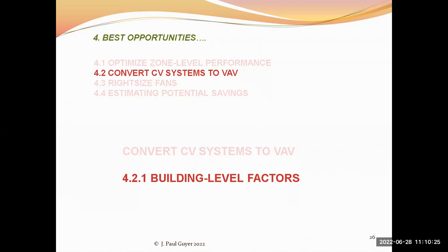In older buildings also, something that you need to be aware of is whether there is an asbestos issue in the building itself. And the rules of the game basically with asbestos are that you can leave the asbestos in place if it's not going to be in occupied spaces.